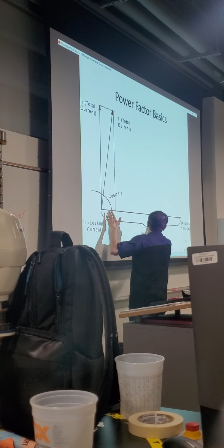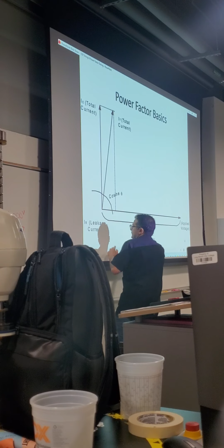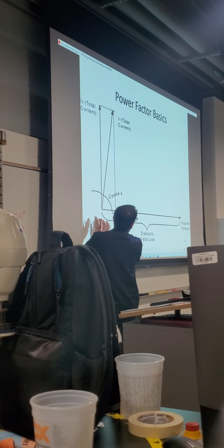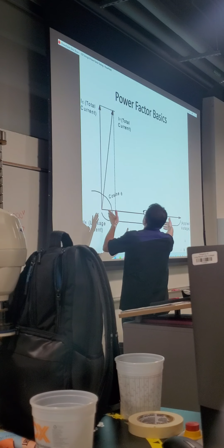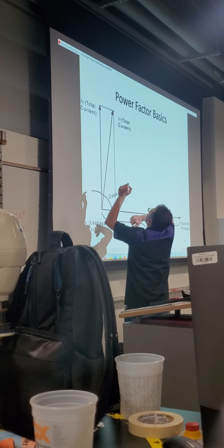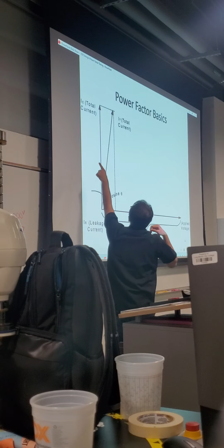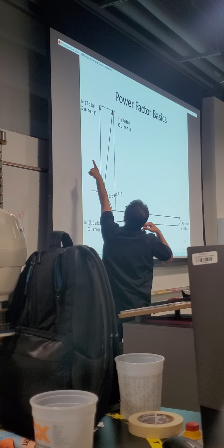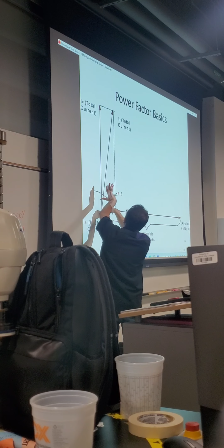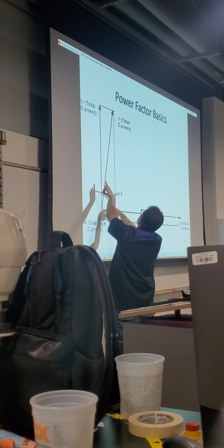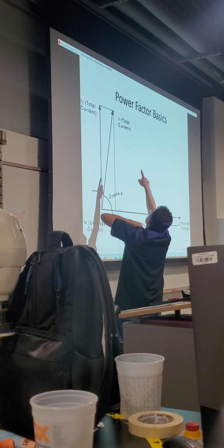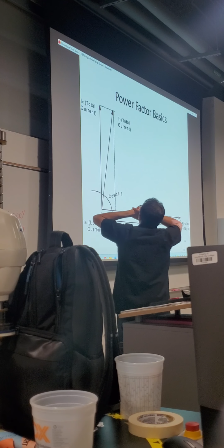This is the dielectric watts losses or leakage current, IR, and that's what we measure using a megger, the leakage current. The vertical axis is your capacitance current. And you have a vector diagram, so this is the vector summation of the two, and I sub t is the total current.